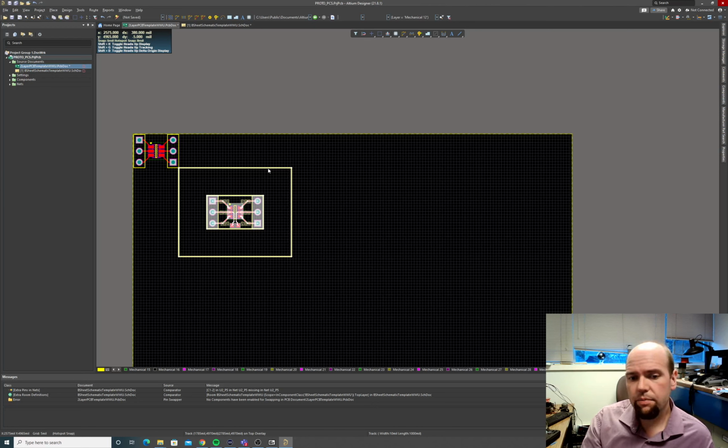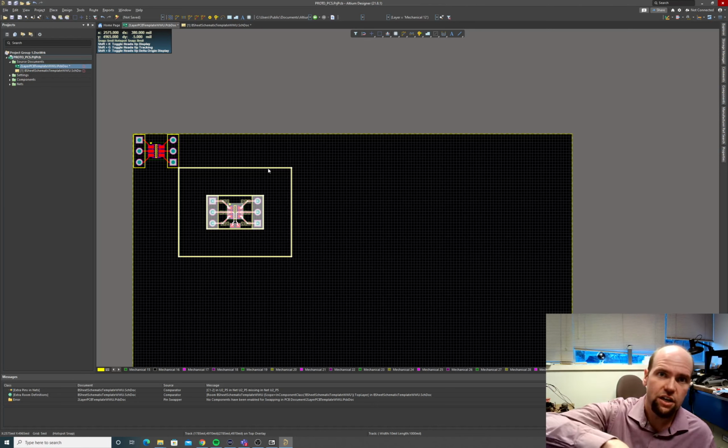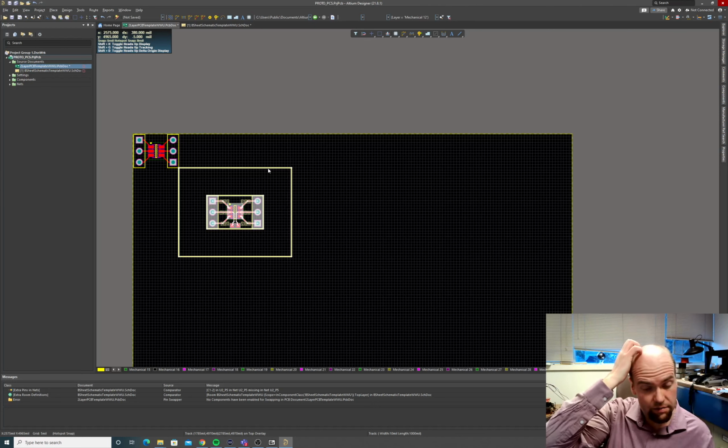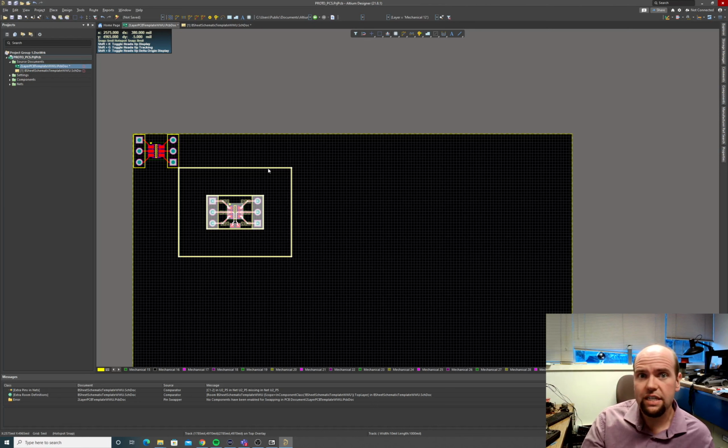Another thing I want to talk about briefly is that a lot of times you'll see boards where the parts are separated like this, and they'll do drill hits right next to each other. So they'll do a bunch of drills, so it only leaves a tiny hair's width of fiberglass in between those drills, and it allows you to break them apart by hand. Most fabs don't like it if you do that. So if you know the fab and you know they're okay with that, that's one thing you can do to make breakaway boards, where you cut a channel between the components and then leave a couple of adjacent drill holes holding it together.